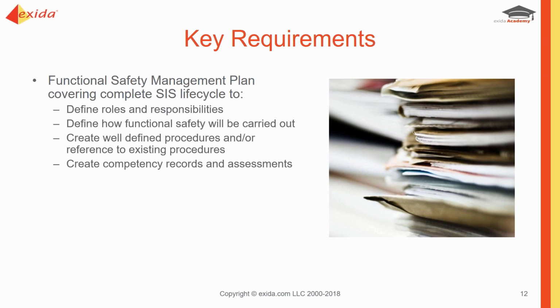We can create competency records and assessments. Here again, this is another major requirement of 61511, competency. So not just defining roles and responsibilities, but making sure that the people in those roles with those responsibilities are competent to do that. So competency and assessments is very important. 61511 requires periodic, and it doesn't define how often that is, ongoing assessment of our personnel.